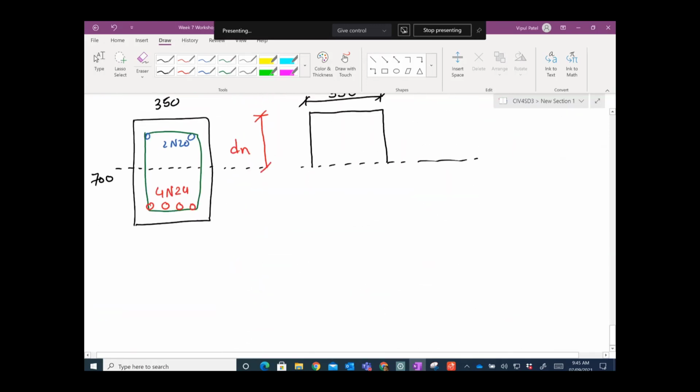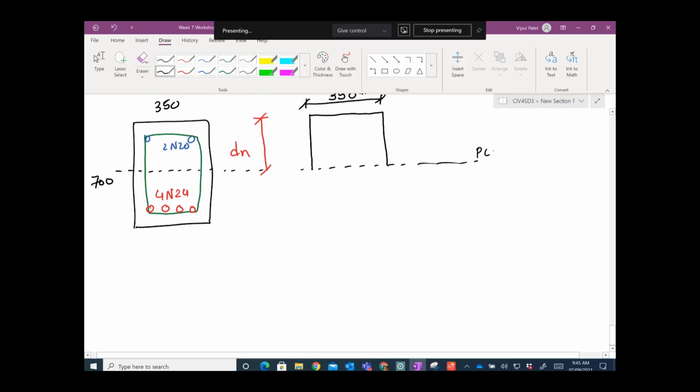Now this is the plastic neutral axis. This is PNA, plastic neutral axis, not ENA. For the plastic neutral axis, our concrete will be cracked below this neutral axis, and the concrete will not be considered as effective concrete. Now we have a simple assumption saying that we can't work with two materials in the plastic zone. We can't have concrete and steel and then apply this equation. These equations are pretty standard, meaning they work for only one material. So we have steel and concrete sitting together, and we need to convert.